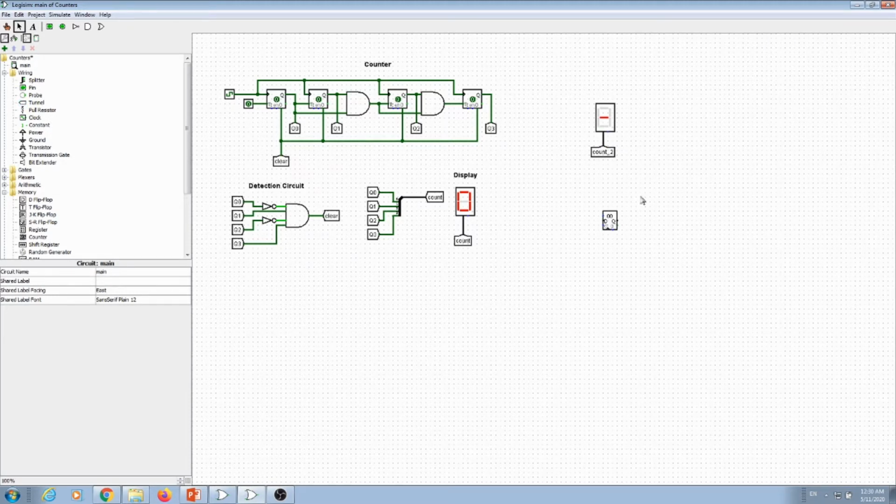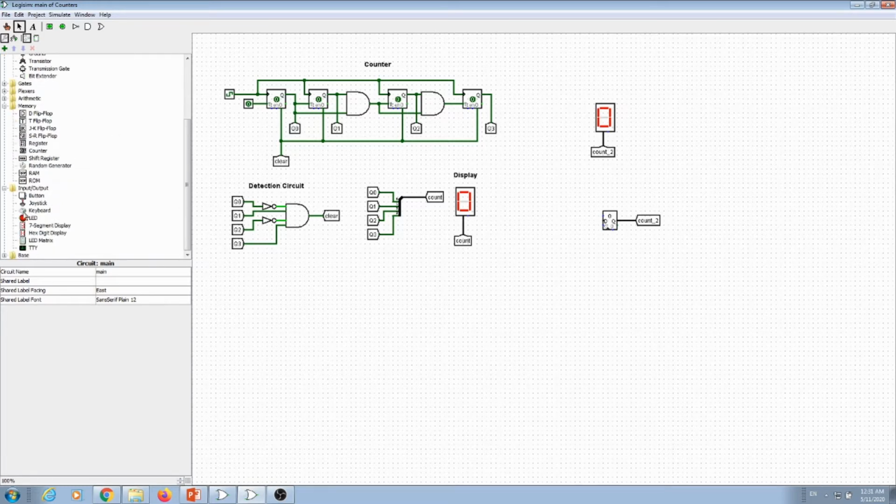I'm going to connect that to my 7 segment display, or hexa display. And the output of this counter, current value, is going to have that label. So 4 bits facing west, let's put it here. I need to change the counter to 4 bits too. Now I'm going to give it the clock, but I'm going to use a button to see how it works first.